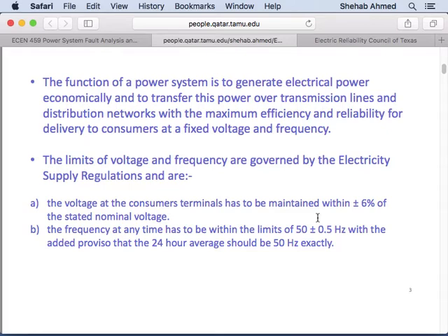So if I have a 10 kilohertz frequency, the speed of induction motors that you just plug in, the fridge, the air conditioner, the lathe in the workshop, the blower, and all of these devices, you want to operate them at useful speeds, right? The useful speed is not 10,000 RPM for a motor that runs an air conditioner compressor, for example. So if I chose a very high frequency, then all the devices that I'm going to be plugging into the utility have to operate at that frequency.